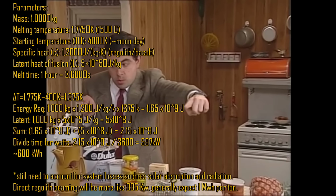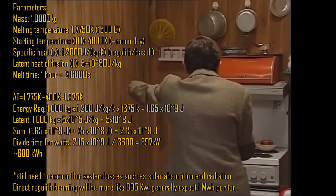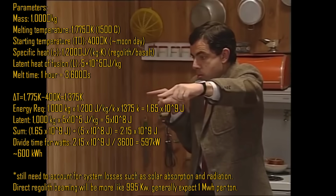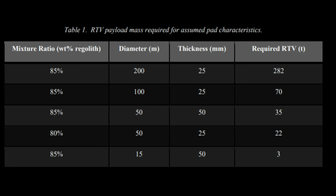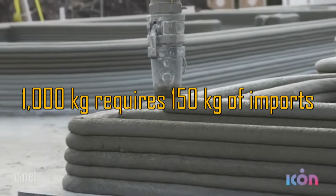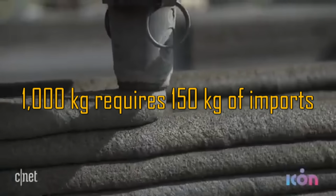To melt regolith for casting requires about 600 kilowatt hours per ton, so we can probably make 1 ton of cast regolith bricks for about 1 megawatt hour. The ratio of regolith to plastic binding or vulcanizing agent varies, but it's typically something around 15%, meaning for 1 ton of 3D printed stuff, we need to import about 150 kilograms of vulcanizing agent, or plastics.